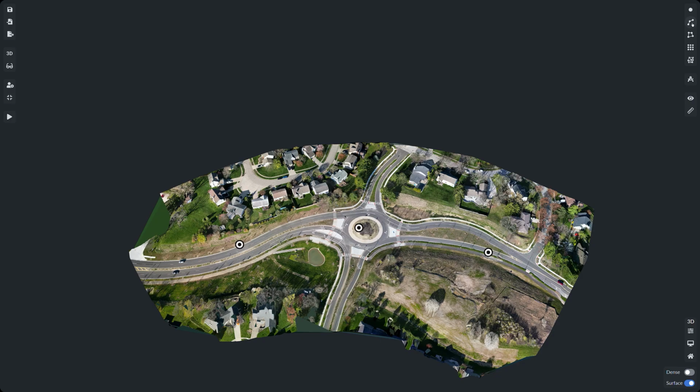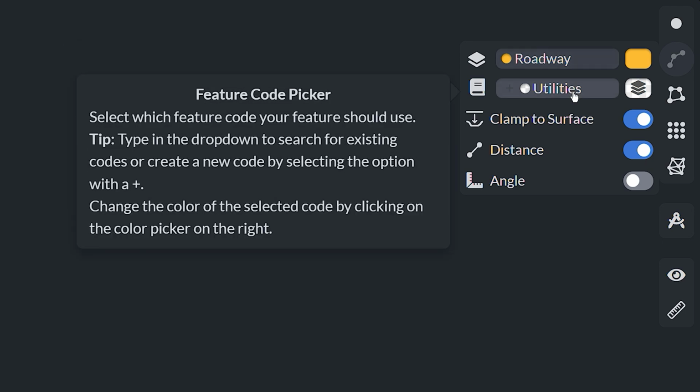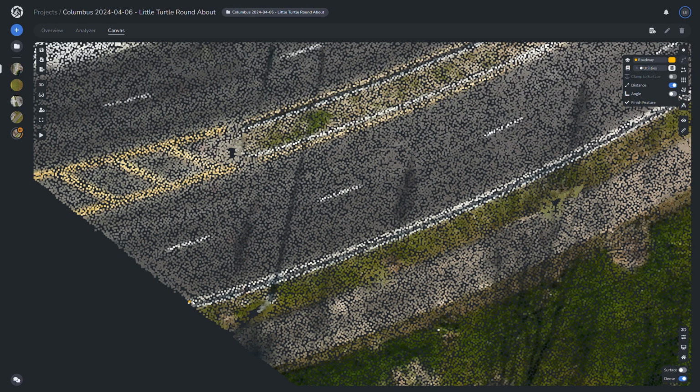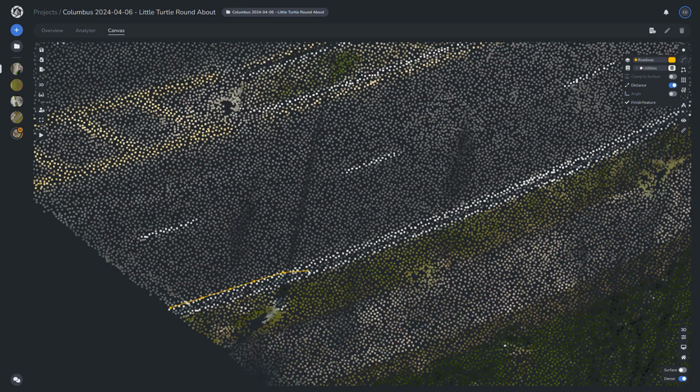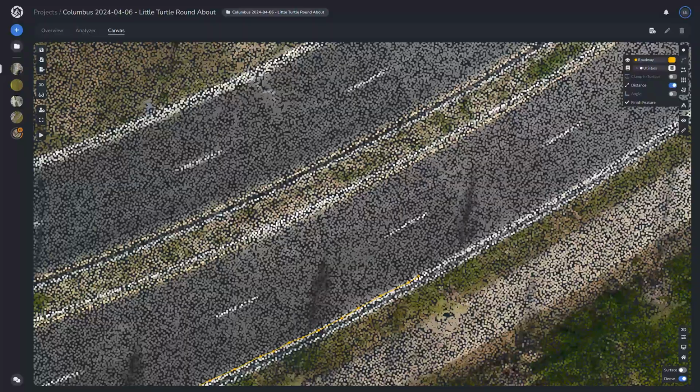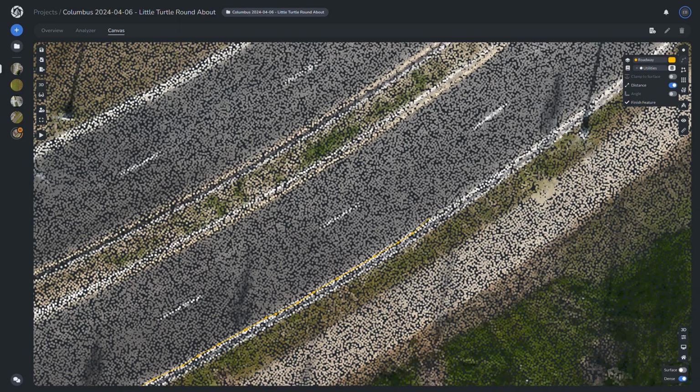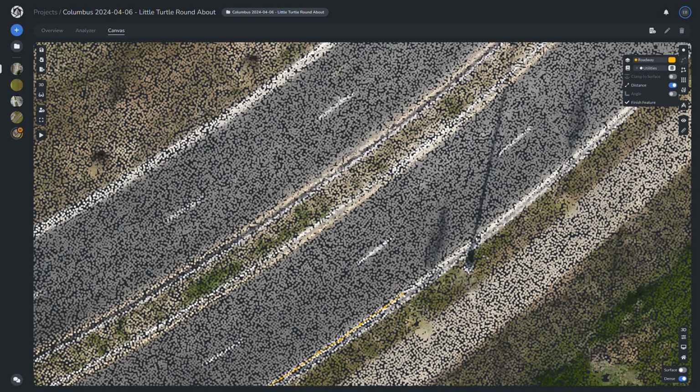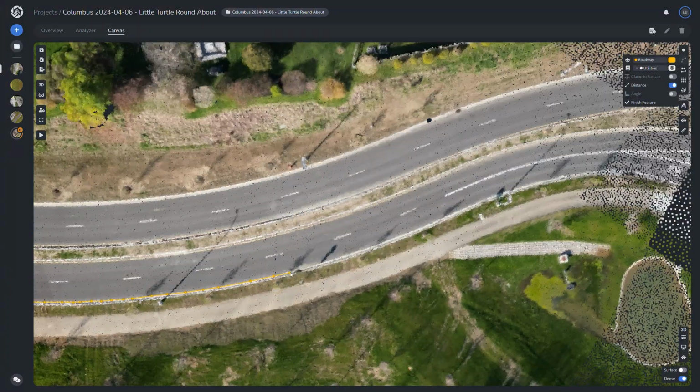To add a polyline, you can select and label your layers like before and create a connected sequence of line segments. Polylines are commonly used to represent linear features such as roads, rivers, railways, boundaries, pipelines, and other linear infrastructure on a map. Each polyline in GIS annotation can be associated with attributes that provide additional information about the feature it represents. These attributes can include things like the name of a road, the type of infrastructure, or any other relevant metadata.